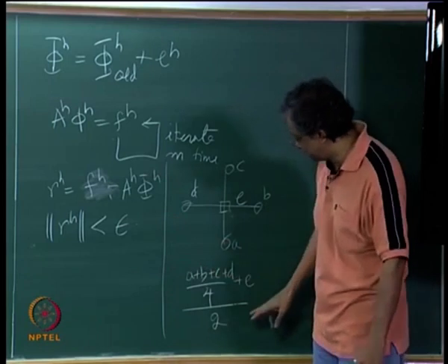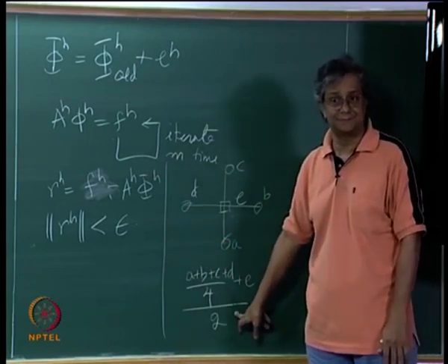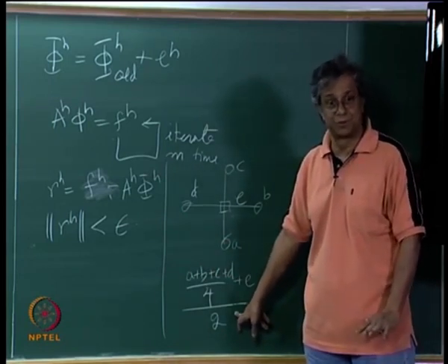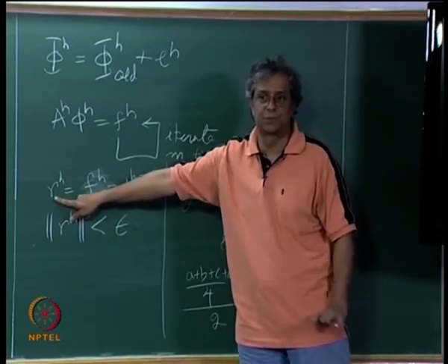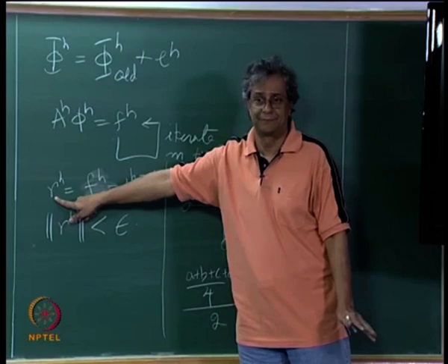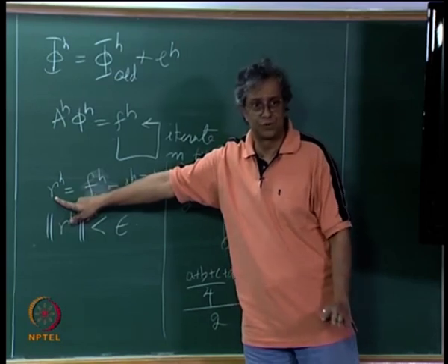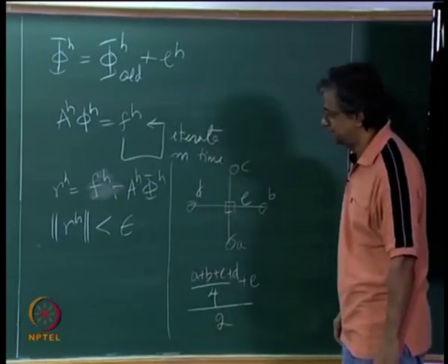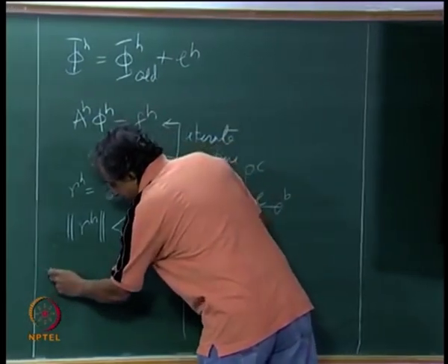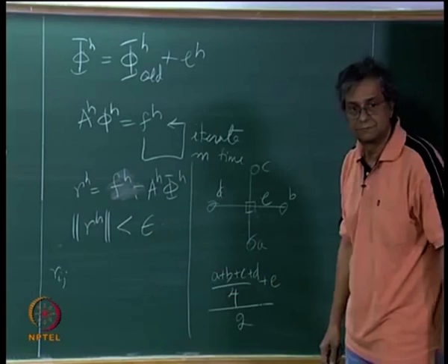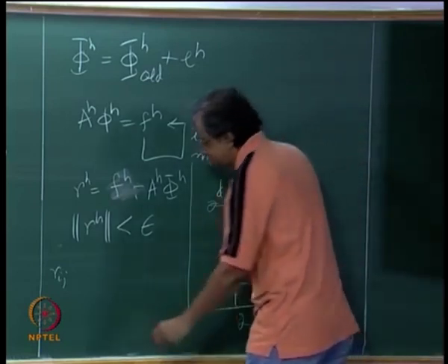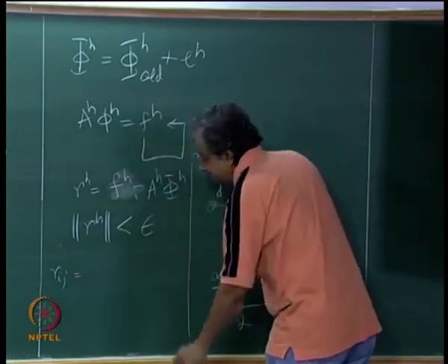So what I am going to do is, I know the Laplace operator will do it for me. I am proposing to smooth R before I do the transfer. Am I making sense? I am proposing to smooth R, this is called Laplacian smoothing. So you would write R at any grid point as